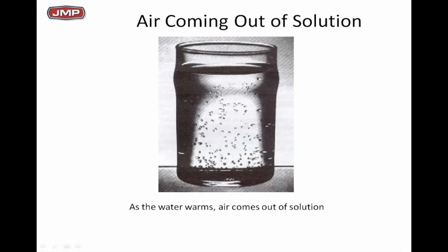So I wonder where the best place would be for an air separator. Well, wait a minute. You're telling me hot water and low pressure. You got it. That would be where you want your air separators to be. So the lowest pressure possible with the hottest water.